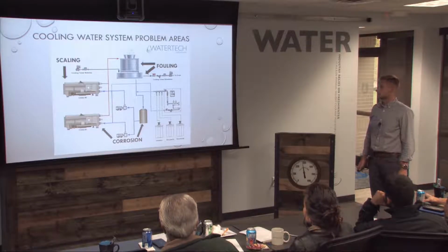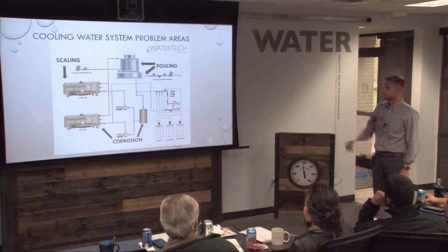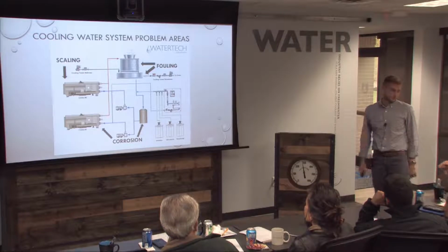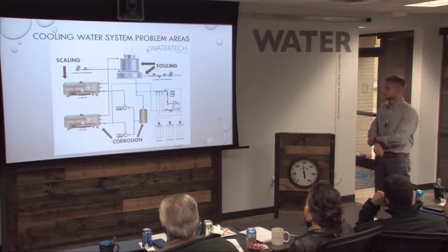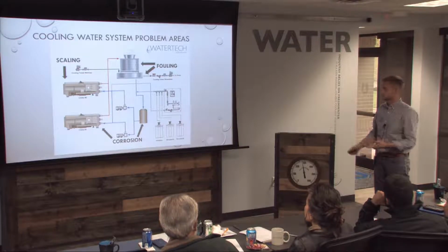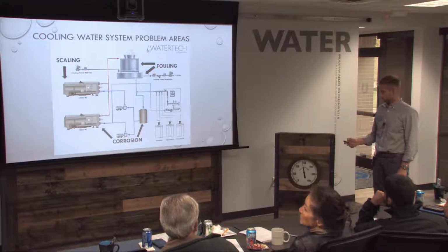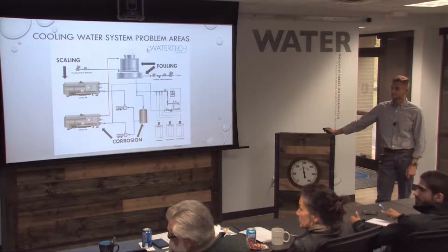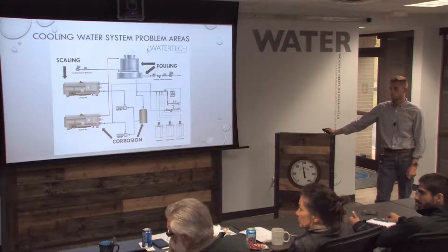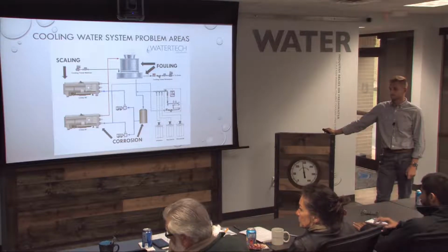That's where you'll get a lot of microbiological issues, whether it be like a film or some algae growth on your fill. I don't know if anyone has seen that before. And on top of that, some corrosion. So, around some good show and tell corrosion inside of that elbow. Scale buildup in this one. More on this one. Yeah.